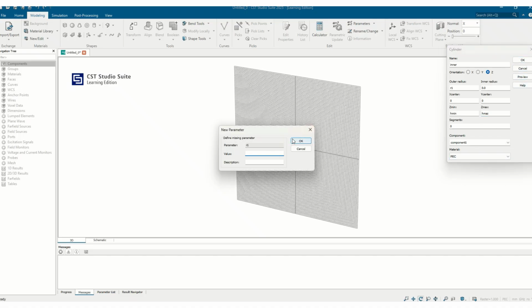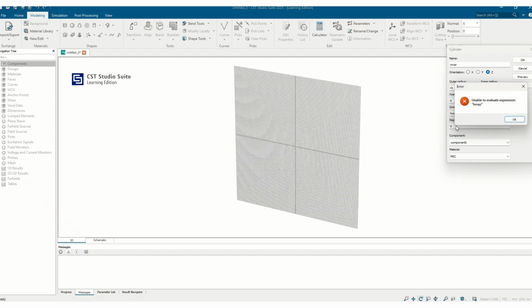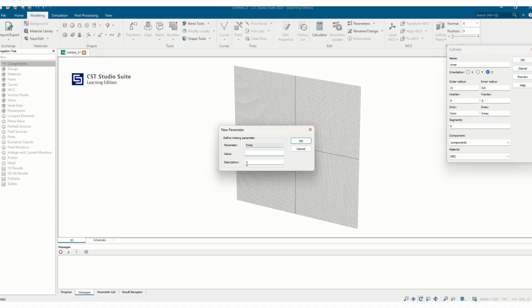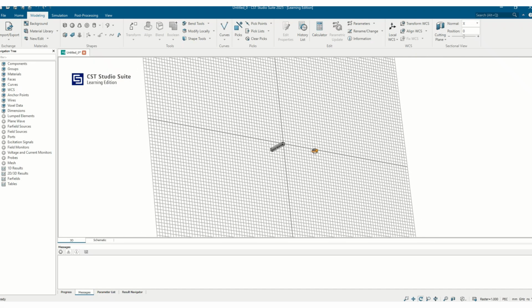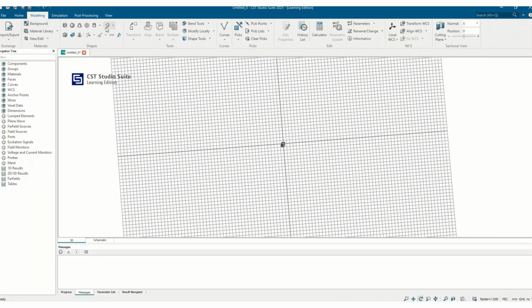So going to click OK. R1 is 0.45. H minimum I'm going to put as minus 6 mm. H maximum I'm going to take as 0, because my purpose is just to analyze the characteristics of this SMA connector.